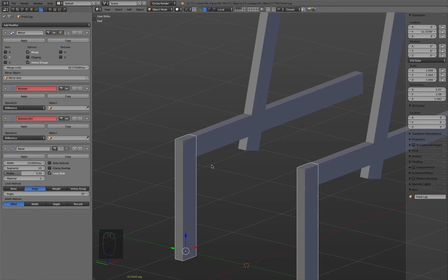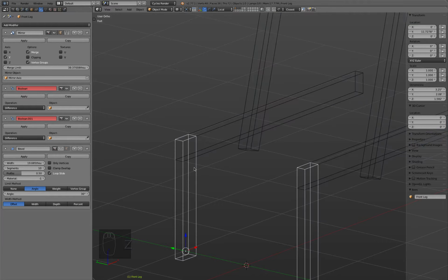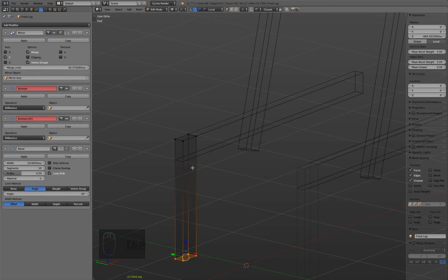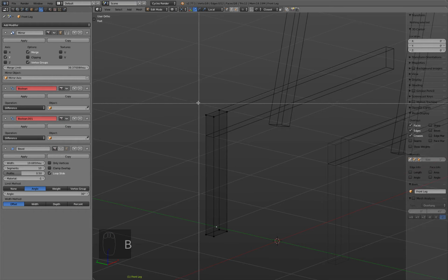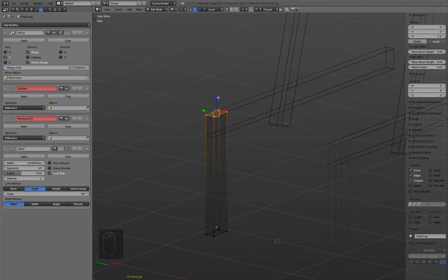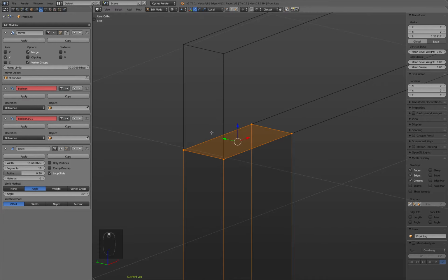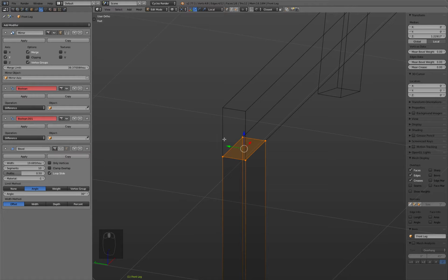So in direct modeling, that basically means we do not use an interactive way to do volume or surface calculations. We just build the detail by hand. So let's start with this one. The first step would be I have to only select the upper faces, and then I move these faces down and snap to this lower edge. Perfect. Okay, so now I have a basic butt joint, and again, that doesn't really work very well.